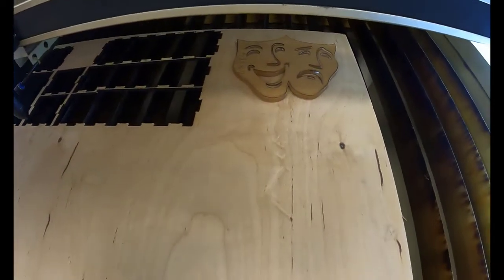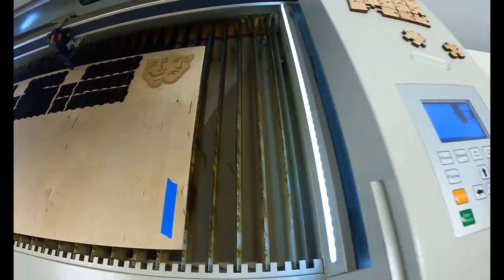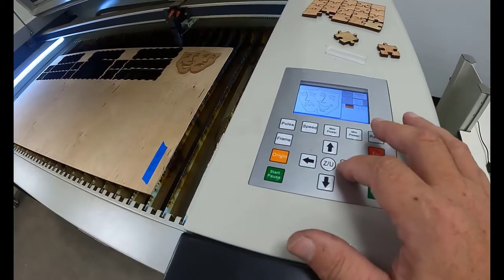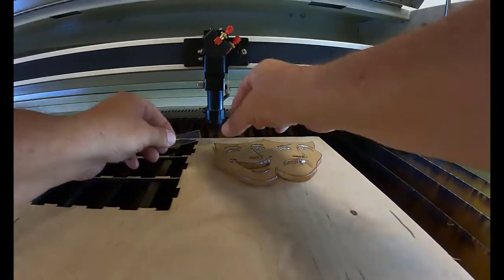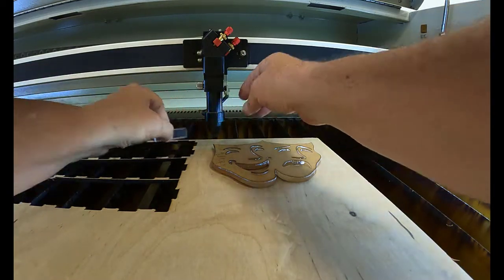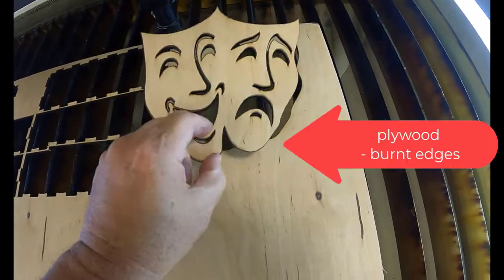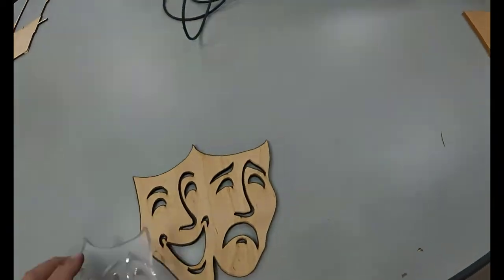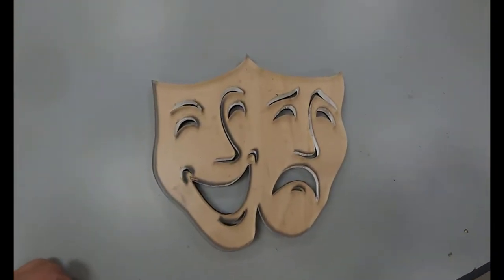So we're going to take this same design and cut it out of plywood so we could have a plywood backer on it if we wanted to behind the acrylic, or do a variety of things like paint it and put silver paint on it to make a mirror if we wanted to. The key element here is we need to recalibrate the laser because the plywood is a different thickness than the acrylic, so we have to go through the whole process all over again. The exact settings worked on plywood, so the laser speed and the laser power worked out perfectly. Things went through, things cut, and we can compare and look, make sure they cut the same size.